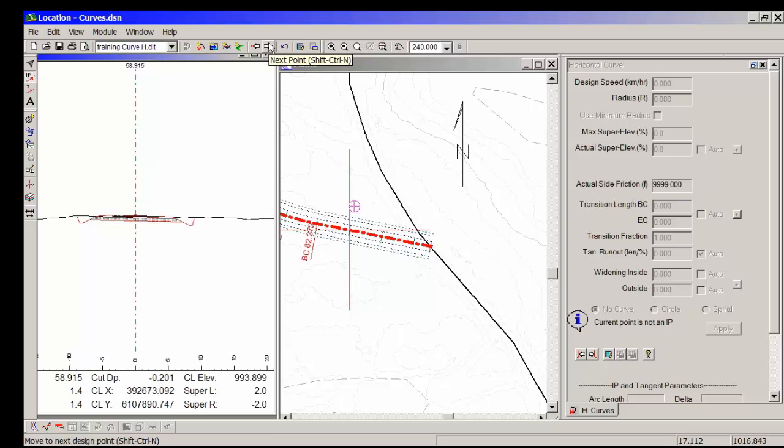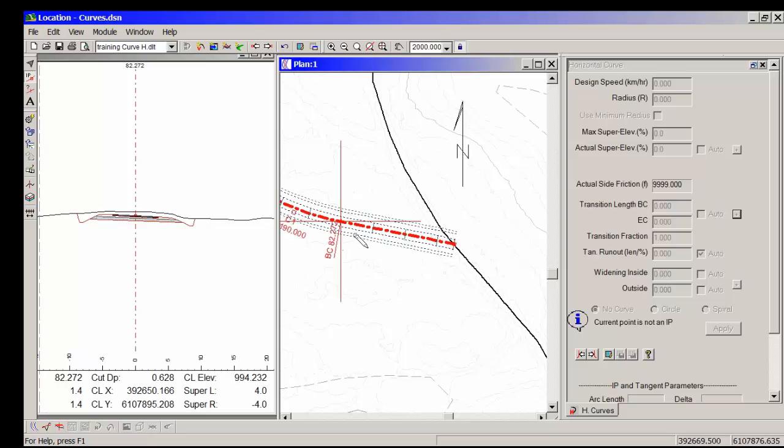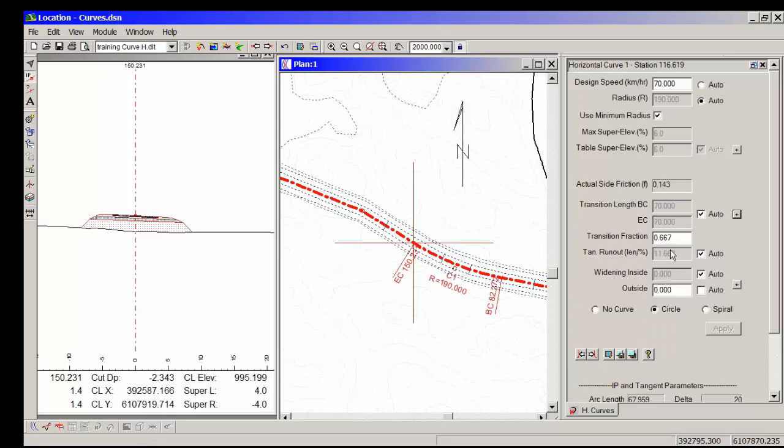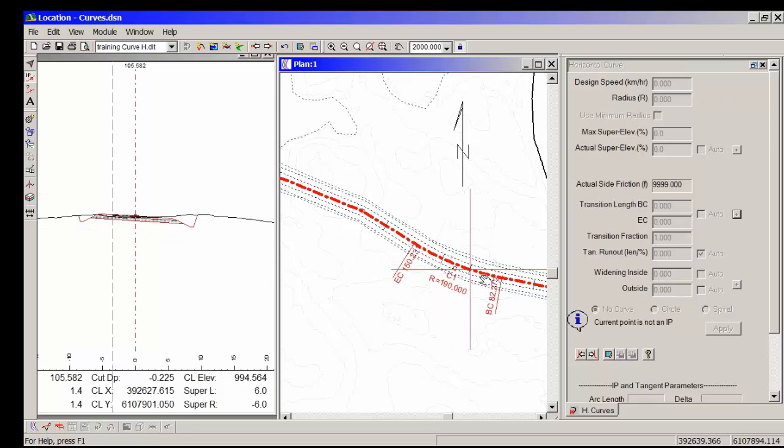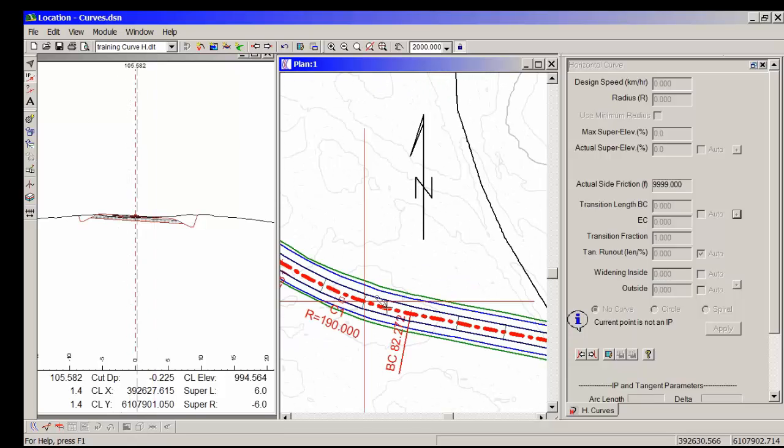We're actually going from superelevation runoff to runout, through the superelevation runout, and then coming to full super right here. So no, sorry, we're at the 2/3 point here, because like I said, 2/3 of the transition occurs outside the curve. So if I go back, this is where we're at full. So this distance right here from this little green dash to the begin curve is the 1/3 distance that we needed to get to full super.